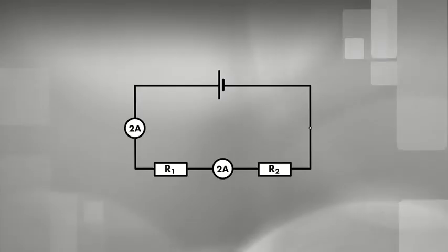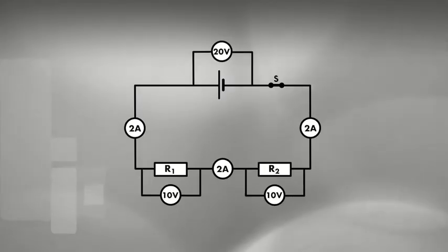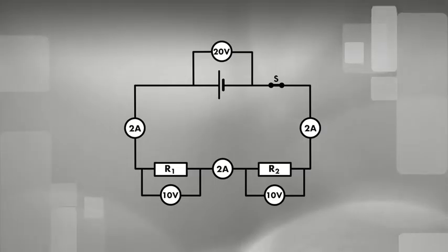So do our experimental results agree with these principles? Well, yes. The total potential difference across the cell is 20 volts. So the potential difference across resistor 1 is 10 volts, which means that the potential difference across the second resistor, R2, must also be 10 volts. A series circuit of 2 identical resistors splits the potential difference in half. Half of the PD is applied across the first resistor, and the other half is applied across the second resistor.